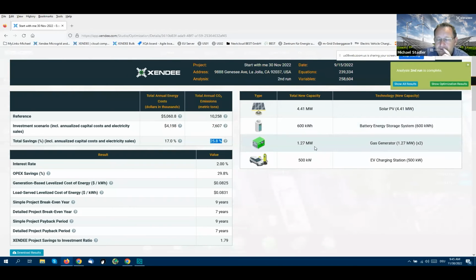And this is really interesting now, because again, I would think that a lot of people would think you have a larger PV system here, so you also need a larger battery system, but that's not what it is, because it figures out that a battery has charging and discharging efficiency, right? So in terms of carbon emissions, you're actually losing energy and you're creating inefficiencies and carbon emissions. This is why it's better to use the PV electricity directly. So it's actually better to oversize the PV system a little bit, use the energy directly during the day and not put it too much into the battery. This is why also the battery size is going down with a carbon reduction. But of course, as everyone would expect, also the CHP system is reduced from 3 megawatts now to 1.3 megawatts, because we put the focus on carbon reduction. And of course, this will change the operational behavior again.